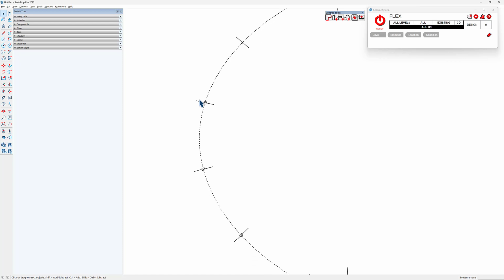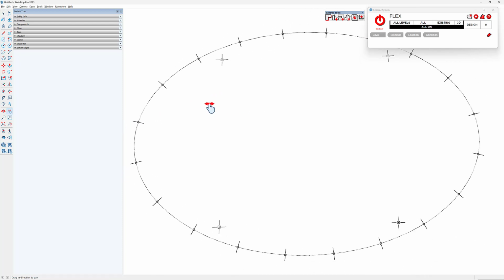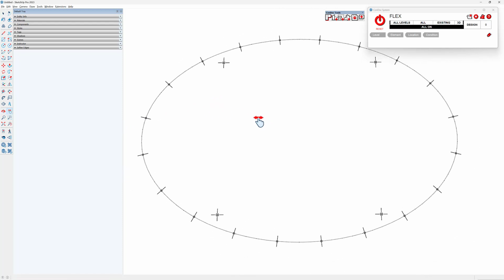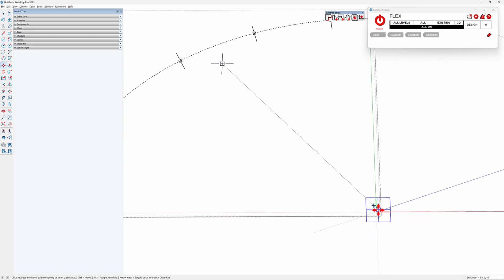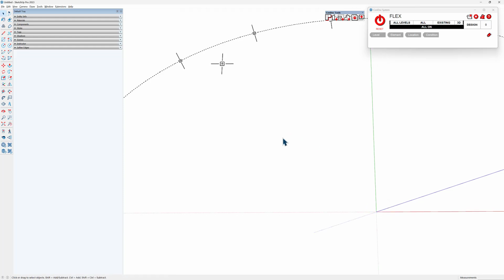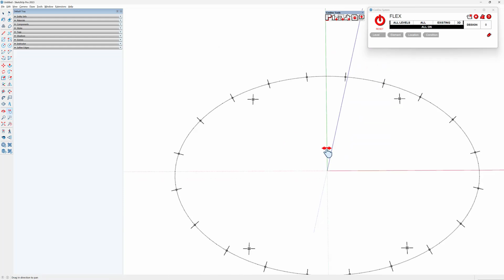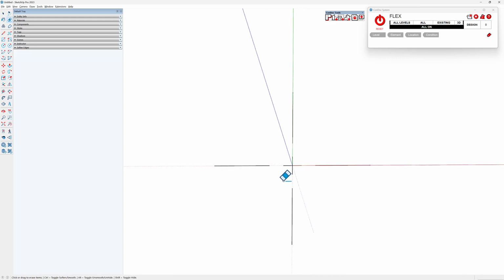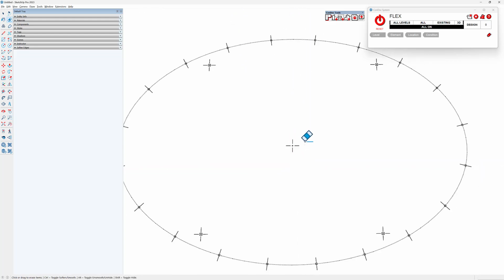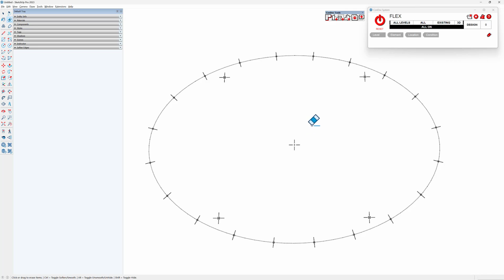All right, so now we get these perfect angular column center lines that are kind of spinning out and around. And I suppose one last thing I'll do, I'm just gonna grab this column here and place it right at the middle, and then cut it, and then back out of here and do a paste in place. And then I'm gonna explode it and then get rid of these. So that way we've got some indication of the center line of this entire setup.